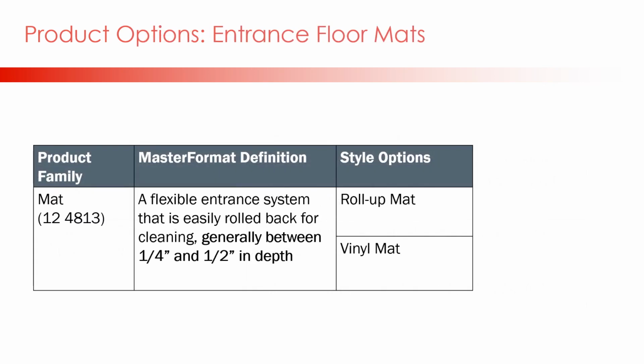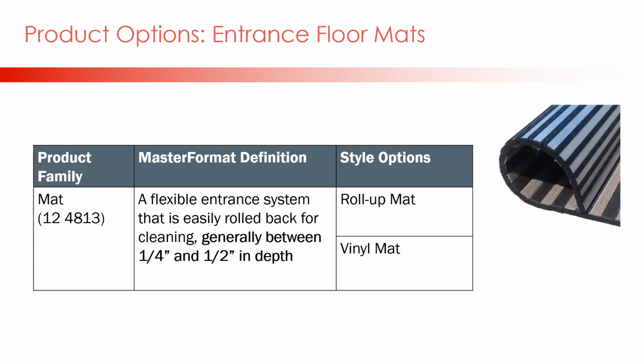We'll begin with a review of the product options for entry mats. As mentioned, they are generally between 1/4 inch and 1/2 inch in depth, can be surface mounted, and meet the 2010 ADA requirements. As reviewed previously, any mat above 1/4 inch depth needs a beveled frame for ADA compliance. Two primary style options in this section include the roll-up mat and vinyl mats.